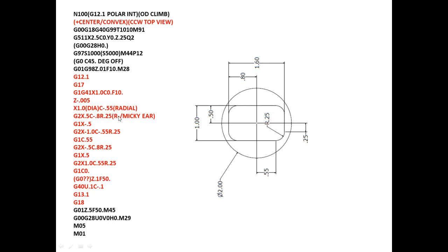And that's why we need to use G41, G42 to control this 1 inch or 1.6 dimension. I guess the customer or operator trying to adjust this 1 inch dimension, which is small, so they just offset it like a normal turning diameter offset. So that's where it starts showing a convex or concave shape.